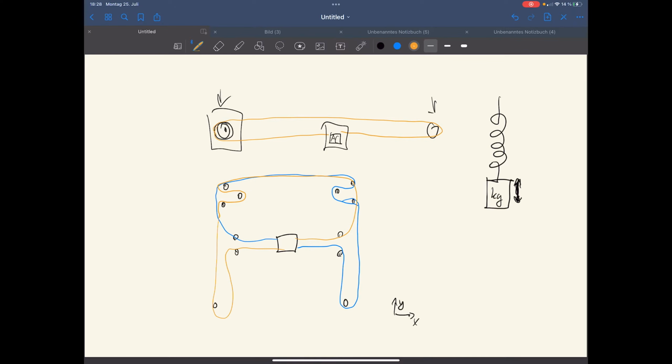And the printer itself will now have 2 resonance frequencies. And why is this the case? Because the belt, of course, when we look at the belt itself, it's a spring all the time, and the same spring. But for movement in X direction, we have a different mass than for the movement in Y direction. This is because in X we only move this printhead, and if we move in Y direction, we move the printhead plus an extrusion here. And we have a different damping factor because one time we have 1 linear rail dampening and the second time we have 2 linear rails dampening. From this we can already deduce how a perfect resonance profile of our printers would look, like a Cartesian or a Core XY.